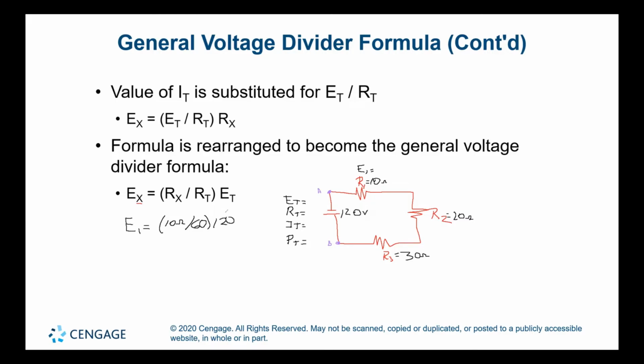So when we do that, what we are doing in reality is getting the percentage of the total voltage that this individual component is taking. And by determining the percentage that each individual component is taking and multiplying that percentage into 120, then we are going to be able to determine how much they are getting, what is the share, okay?